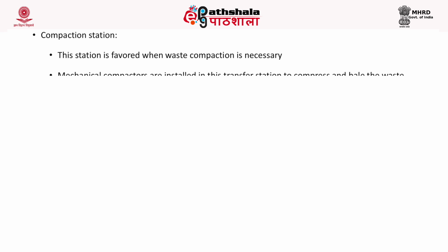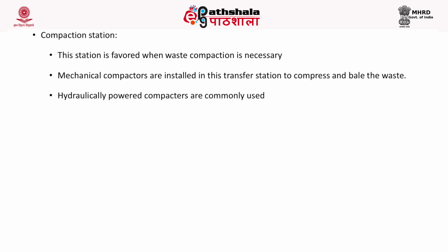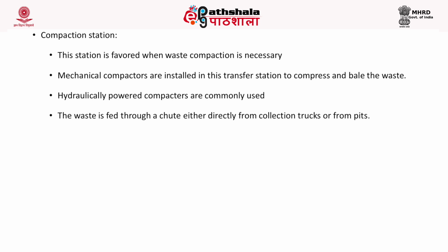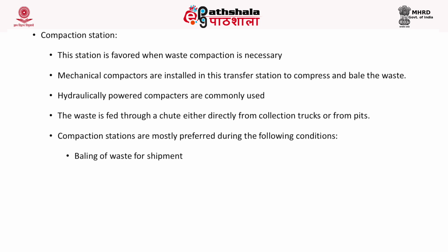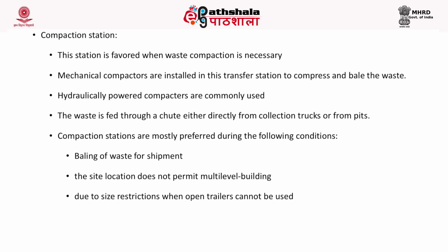The third type, the compaction station. This station is favored when the waste is to be compacted. The mechanical compactors are installed in this station to compress and bale the waste. Hydraulically powered compactors are commonly used for compacting the waste. The waste is initially fed through a chute either directly from the collection trucks or from pits.